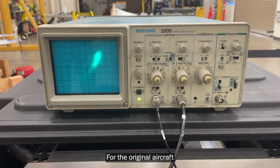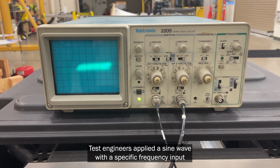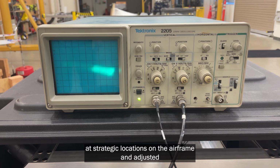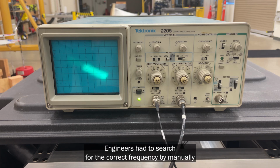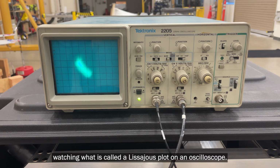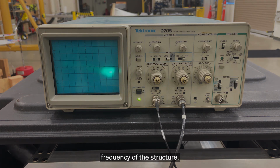For the original aircraft GVTs in the 1960s and 1970s, input force excitation was very simple. Test engineers applied a sine wave with a specific frequency input at strategic locations on the airframe and adjusted that frequency until they excited a vibration mode of interest. Engineers had to search for the correct frequency by manually watching what is called a Lissajous plot on an oscilloscope. If the plot became a circle, they knew they'd found a natural frequency of the structure.